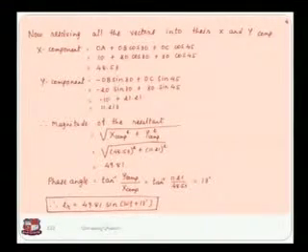So your final equation for resultant is like this. It is 49.81 sin omega t plus 13. This plus 13 indicates your resultant current is leading by a reference axis, and angle from the reference axis to the resultant current is 13 degree.